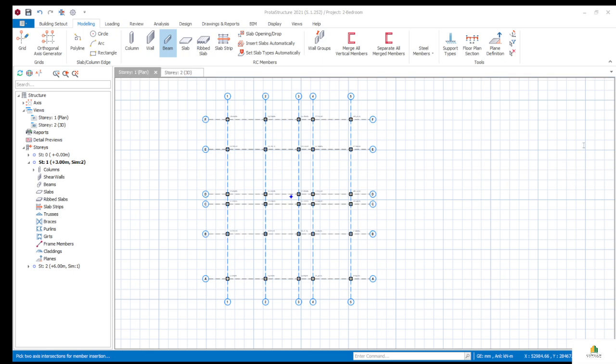Let's change them to, let's say, 300. Let's set the width of that beam to 300, and the depth of that beam to, let's say, 300. Then you will see a label which has 1B1. That means story 1 beam 1. After that, you click update.